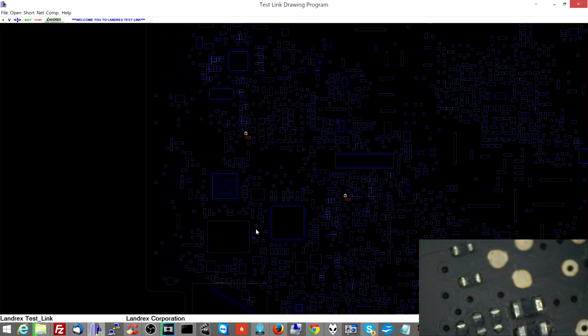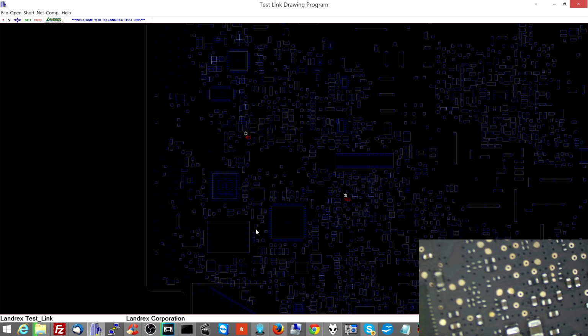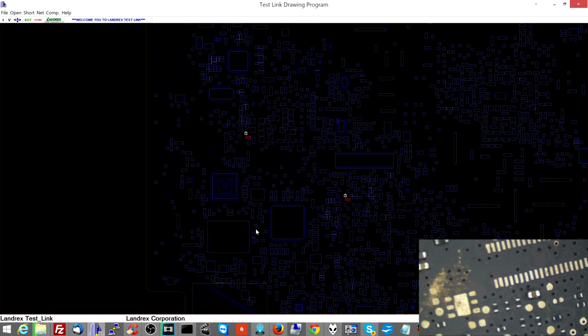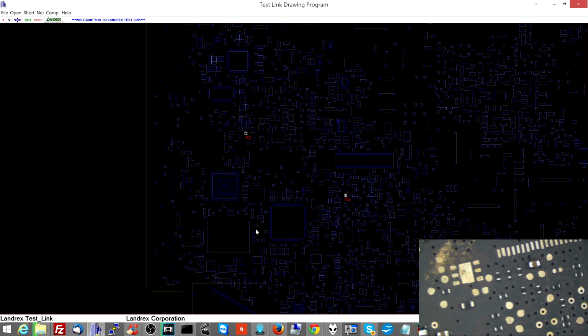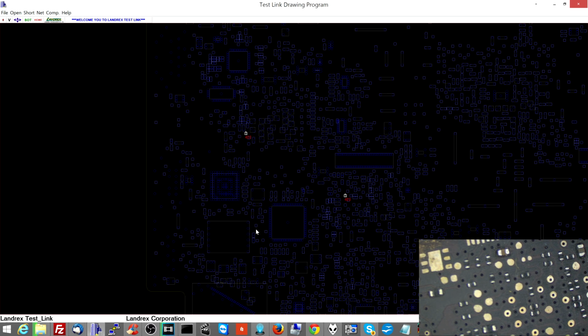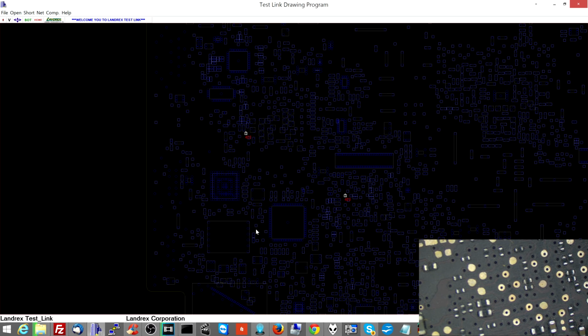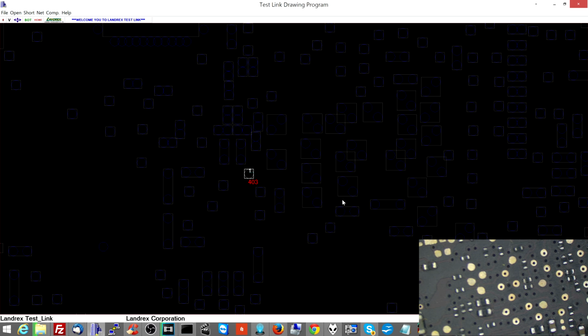All right. PM sleep S5. Where are you? Let's see if you're here. Zoom out. Oh, look at this. You have sprinkled a bunch of probably conductive thermal paste on the motherboard. Thank you. That's probably why this doesn't work. By the way, this is actually warranty. This is somebody who sent it back, and I'm pretty certain this thing got sent back because of conductive thermal paste being all over the motherboard.